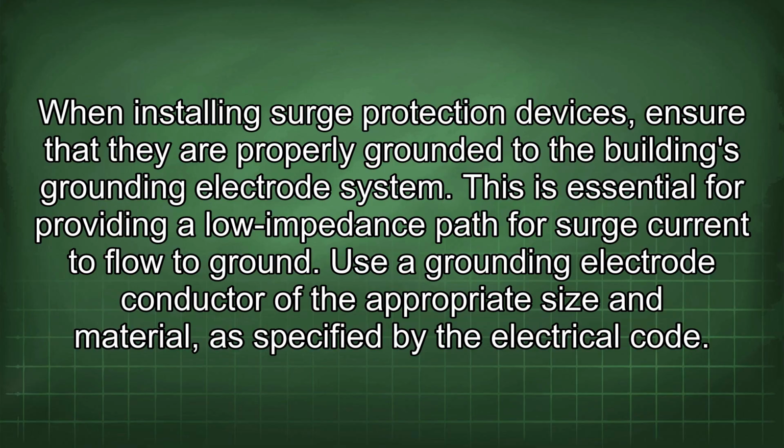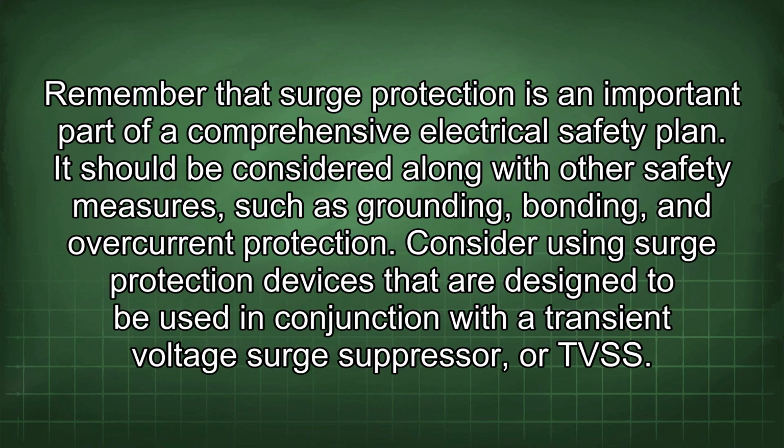Use a grounding electrode conductor of the appropriate size and material, as specified by the electrical code. Remember that surge protection is an important part of a comprehensive electrical safety plan. It should be considered along with other safety measures, such as grounding, bonding, and overcurrent protection.